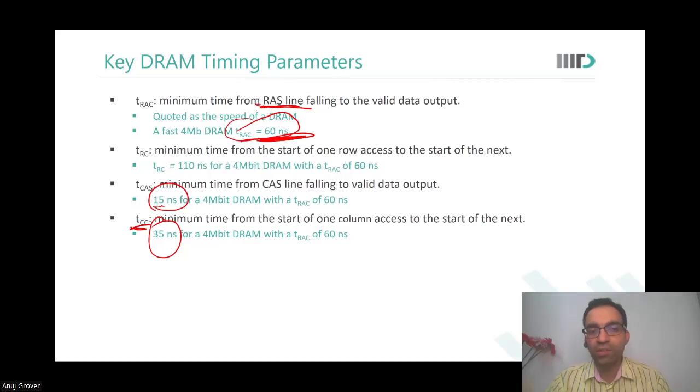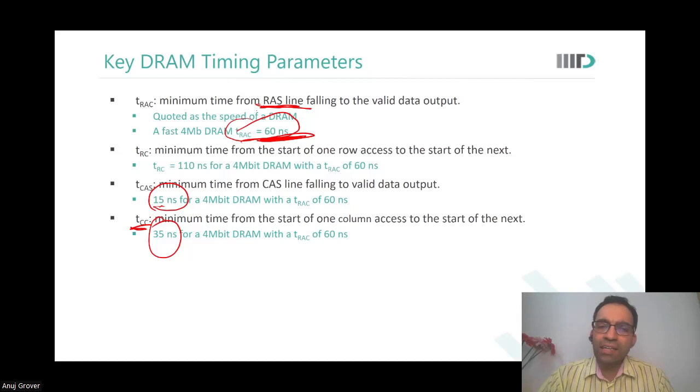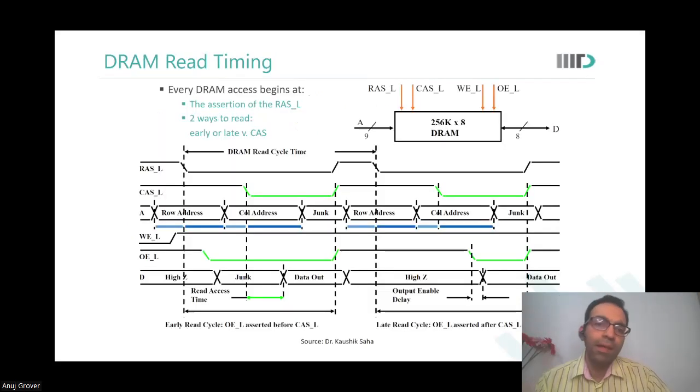What could be the extra stuff involved there? Charging of bit lines. When you change the column address, bit lines are not even being touched. Sense amplifier operation has already happened. It is more about resetting the state machine, resetting the latches, everything, so that the new decoding can now start. Basically settling down. Yes.